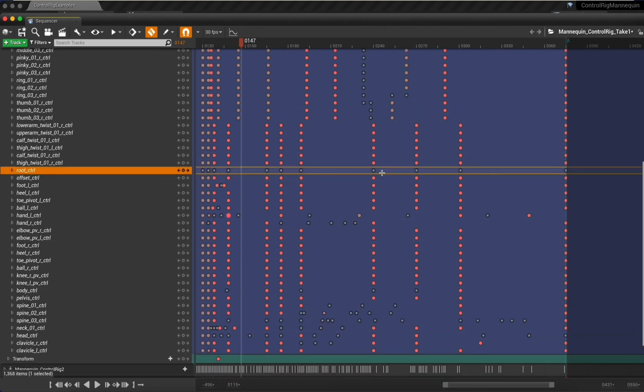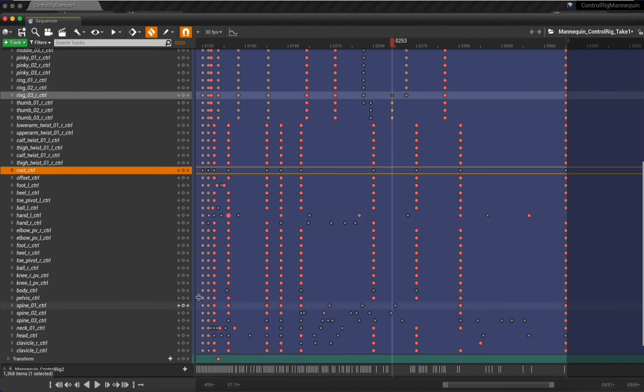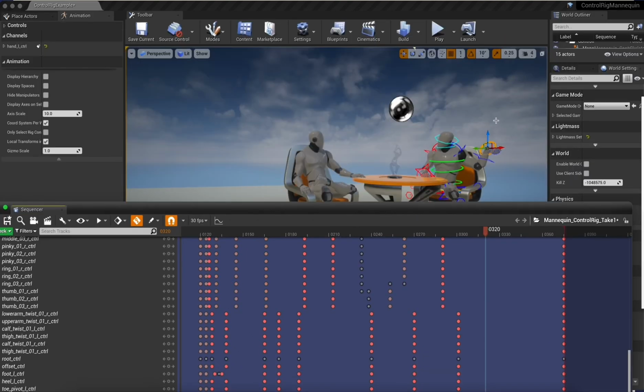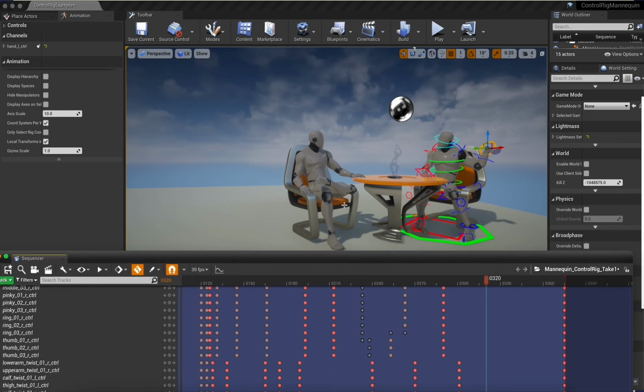So basically, how I change the animation is that I choose the little red point or the gray point here attached to this bone part. For example, I'm gonna change the left hand here, and I click on this button. You can see that this is attached to here, and I can change the position and the angle of this part to reach the final effect. For this character, I did the same thing, and I'm not gonna show you how I did that because it's all simple work, and you just need to adjust every part using these buttons.